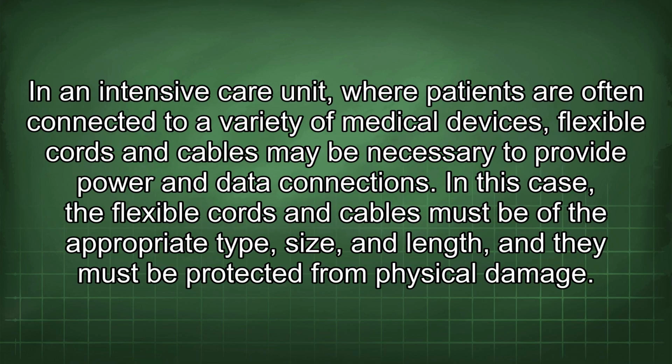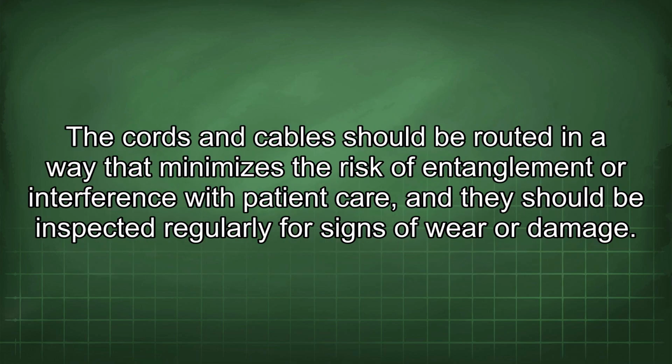In an intensive care unit, where patients are often connected to a variety of medical devices, flexible cords and cables may be necessary to provide power and data connections. In this case, the flexible cords and cables must be of the appropriate type, size, and length, and they must be protected from physical damage. The cords and cables should be routed in a way that minimizes the risk of entanglement or interference with patient care, and they should be inspected regularly for signs of wear or damage.